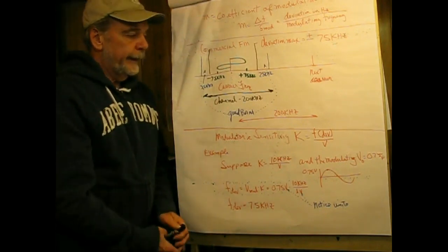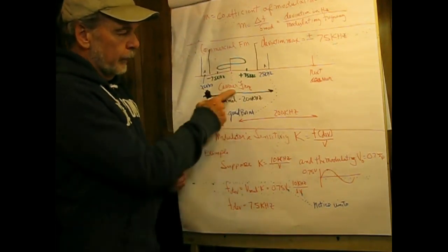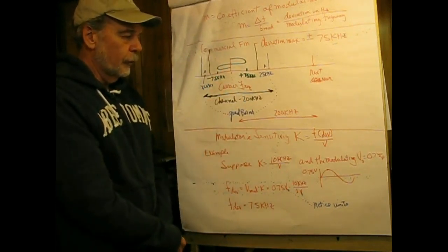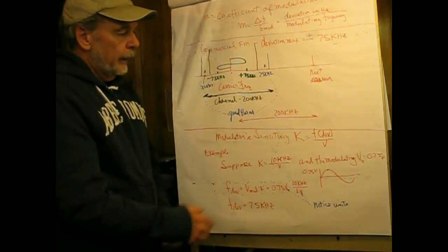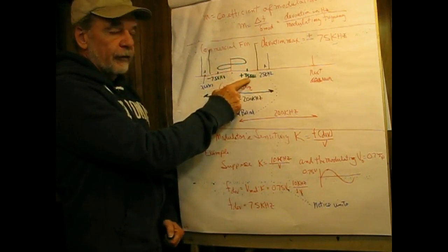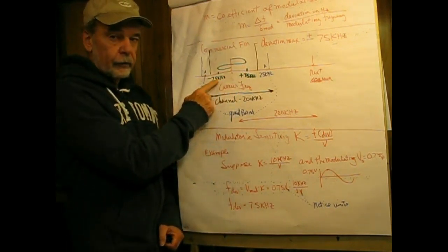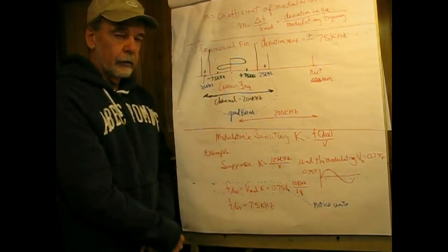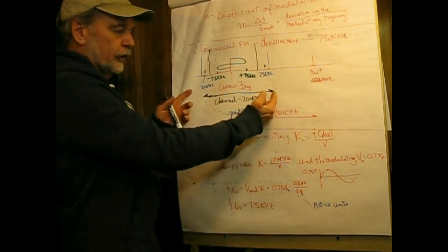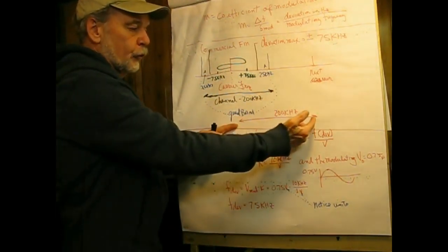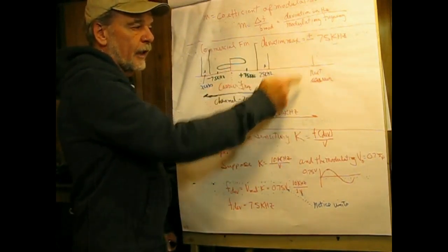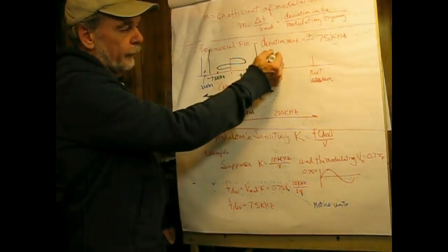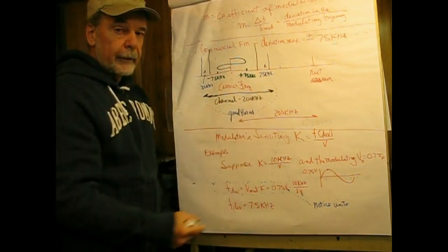And if we just take a look at a channel here, an FM channel, the FCC assigns the carrier frequency, say, I don't know, use a different number, 93.5, and the carrier is permitted to deviate plus 75 kilohertz and minus 75 kilohertz in accord with the modulating voltage. And then on each side of this we have a 25 kilohertz guard band. The total channel spacing is 200K, and then 200 kilohertz away would be the next assigned carrier channel, if you will, radio station. And sitting in here would be another 25 kilohertz guard band.